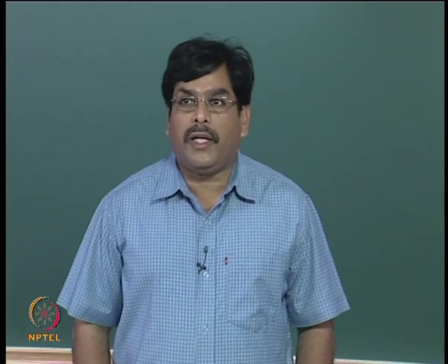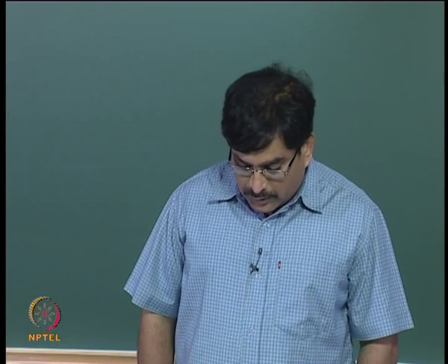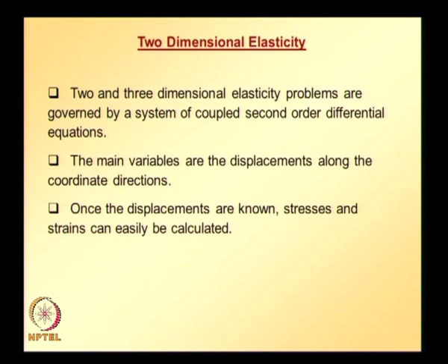So, what we will be doing in the next few lectures, we look at the governing differential equation for two dimensional elasticity problems, and then we look at derivation of finite element equations for a triangular element, 4 node quadrilateral element and 8 node serendipity element.